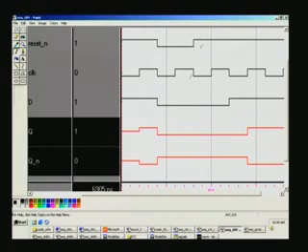Only beyond this the circuit will start working, and now what we have to look for is the clock transition. We have written a positive clock transition. So whatever is the D input, Q will get that value. Now let us see here, it was already cleared. Right at this point reset is applied, right up to this point, and beyond that the very first positive edge clock is this one. At this point of time D is 0, so this 0 goes through and gets registered in Q, and unfortunately this happens to be the very same initialized condition, so you don't see the difference here, but you will see when D is 1.